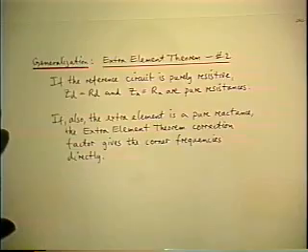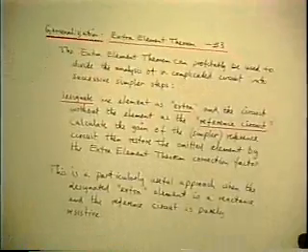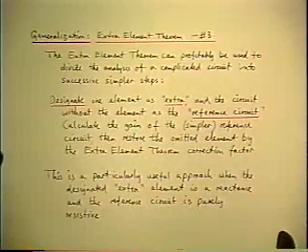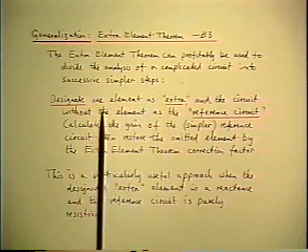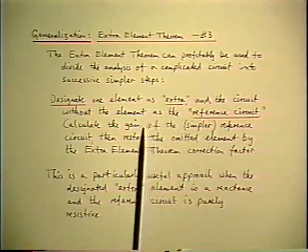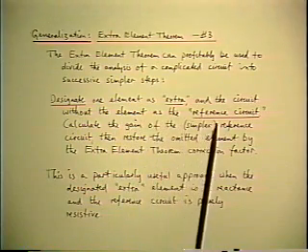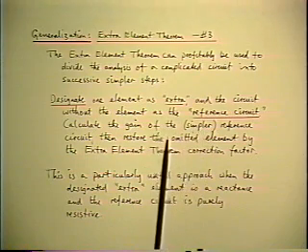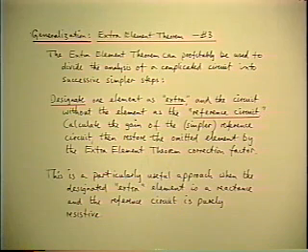So there's the generalization we just talked about. And here's the other class of useful applications. Even if you know everything that's there already, designate one element as extra, and the circuit without that element becomes the reference circuit. Calculate the property of the reference circuit, and then put the element back in.